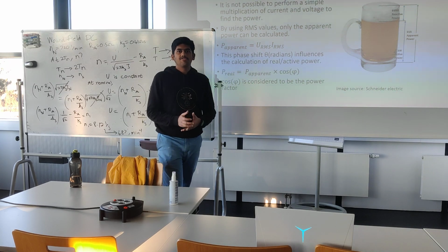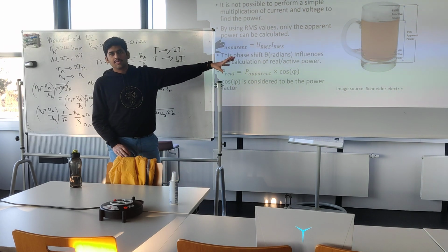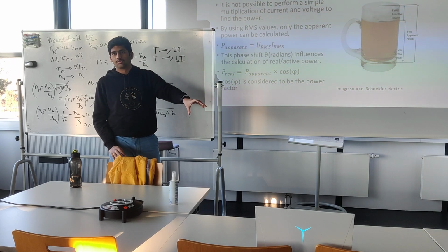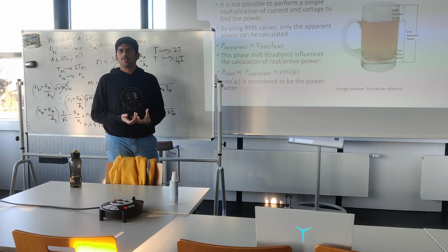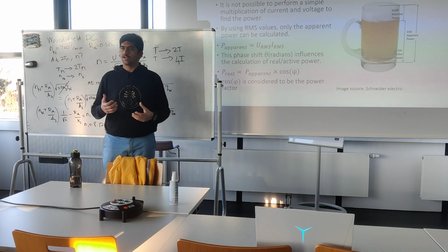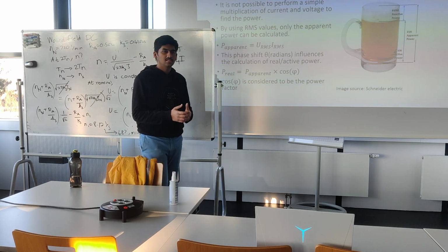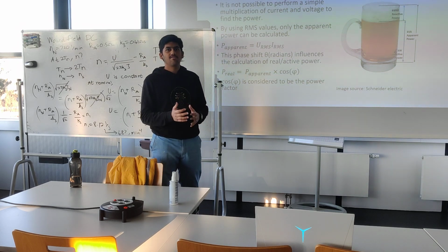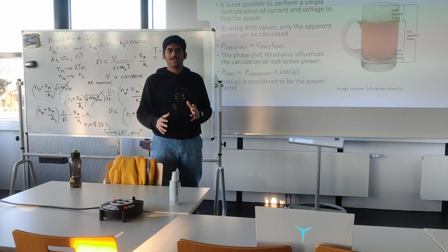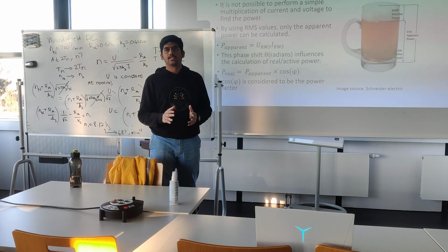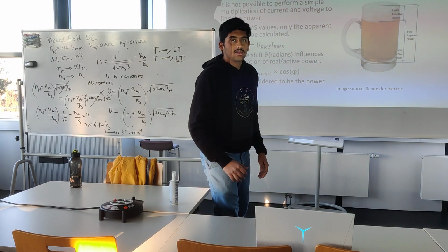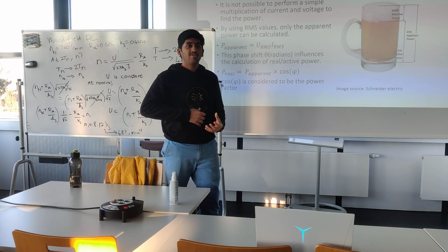But in reality, let's say you have the electrical power supply to mains, and I connect an AC motor. What elements does a motor have? It has resistance because of the armature, but it also has inductance. And inductance creates the phase shift, so you will have some power factor of 0.87, 0.86, 0.8 to 0.9 in that range. Sometimes it's worthwhile to do a power factor correction.